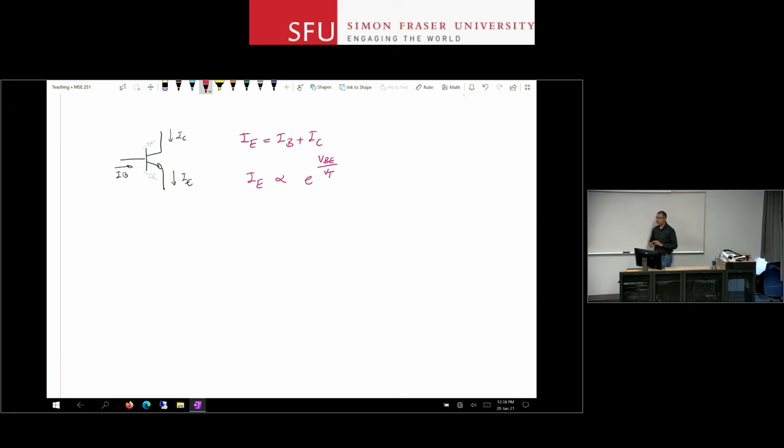Well, when we make these transistors, each one of those junctions behaves very much like an ideal diode with ideal characteristics. So that N is very close to 1 for a BJT. So N is there, but N is 1. So we expect IE to be proportional to the exponential of VBE over VT, just because it's a diode. So some IS times e to the VBE over VT.